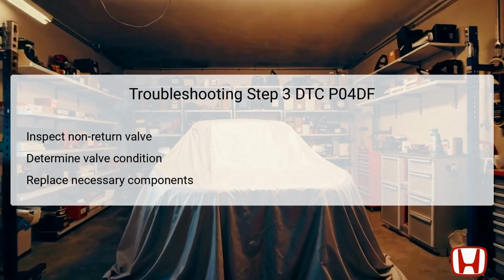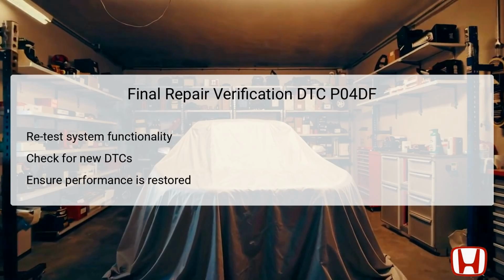The final repair verification phase is crucial for ensuring that all necessary repairs have been effectively implemented. After replacing any faulty components, retest the system's functionality using the Honda Diagnostic System, HDS, to confirm that the DTC P04DF does not reappear. During this phase, closely monitor for any new codes that may indicate other underlying issues.